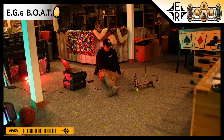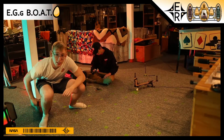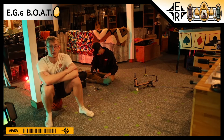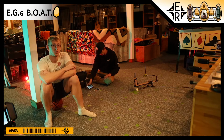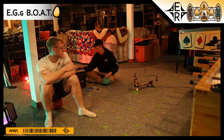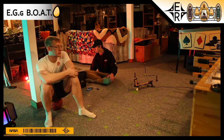We have a question. Do all 3 antennas report something different? Let me get in the camera. I'll take this one. So how it works right now, the first antenna is our reference antenna. That is the one that we will compare the other 2 antennas to. So really what we're looking at is the angle on each of the antennas. We just arbitrarily assign the first one to be 0 degrees,